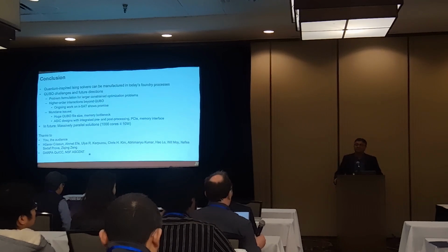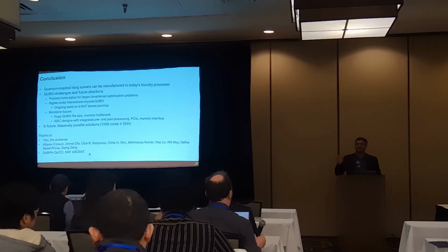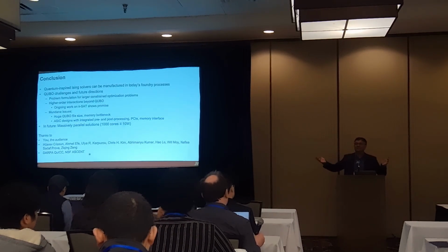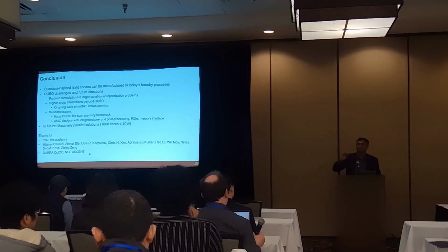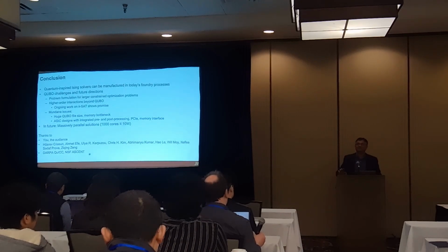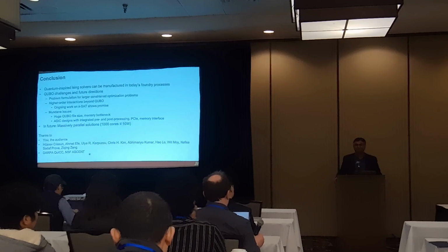There are also other tricks that we've been trying. So instead of working entirely within the analog space, the hardware actually has a greedy one-bit stochastic gradient search algorithm built into it. Basically what it does is it reads the current solution, flips one bit at a time, and it takes a solution only if it gets better. And we've been playing with the precision of the analog oscillator and this digital search, and we found that you can actually trade those off, and that helps sometimes.